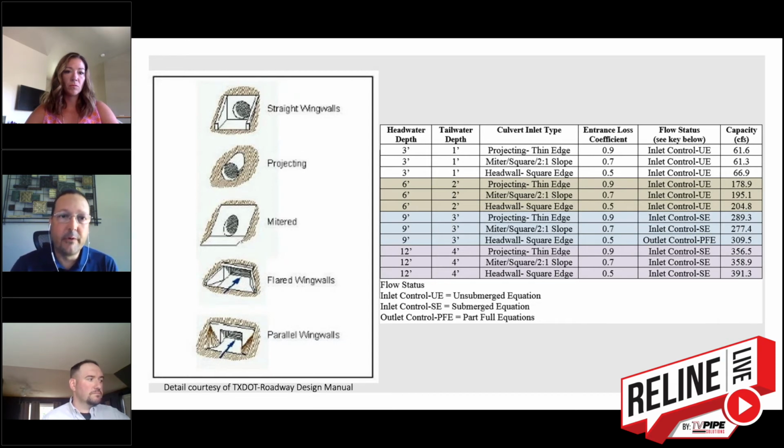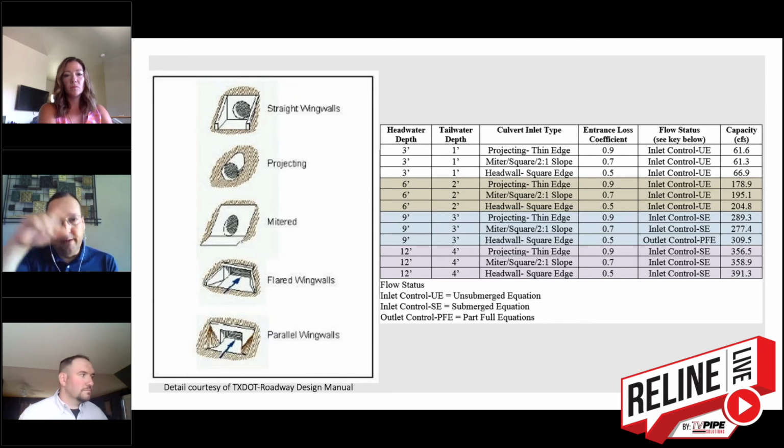It's flame resistant, works well at the end of the culvert. We've created marking lines for cutting, so you can cut the bottom off. So if you want the invert to sit flush, if you don't have, say, an entrance pool in front of it, we do have a flat face to use as a form or to just mount against. We have bolt hole pilot holes marked, and we have a marking line for the circle if you just need a circular shape and you want to get rid of the flat face.